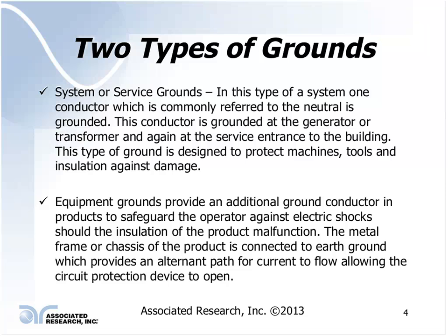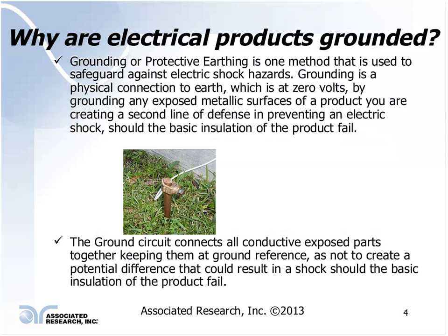Unfortunately, they are one of the most commonly defeated safety features that we build into products today. Because of some of the older systems, people will use a two-prong cord to ground a product that is meant to be grounded. They cut off the ground pins of the line cord. They may be just plugging into an outlet in an older home that may not have a ground circuit, but these are some of the problems.